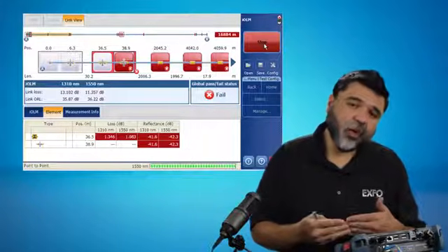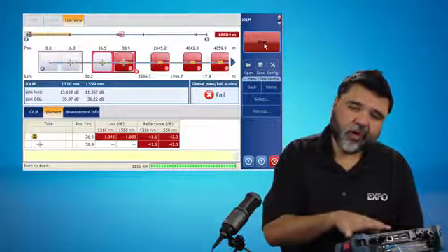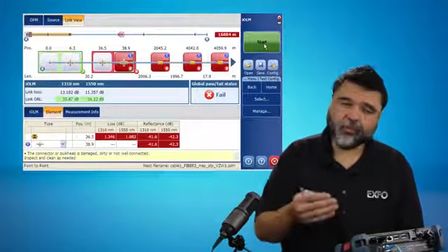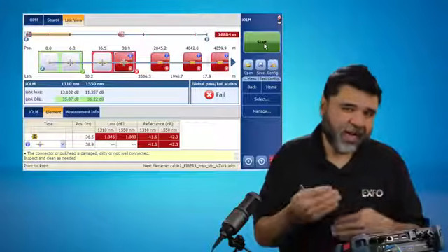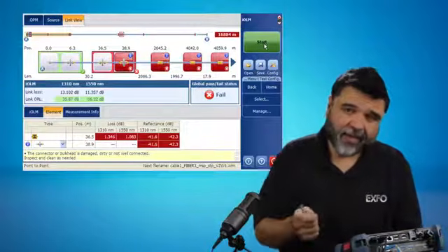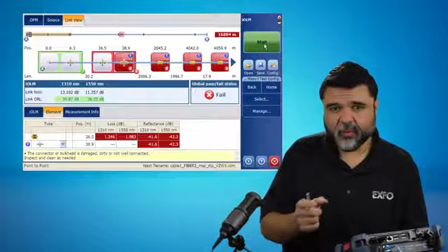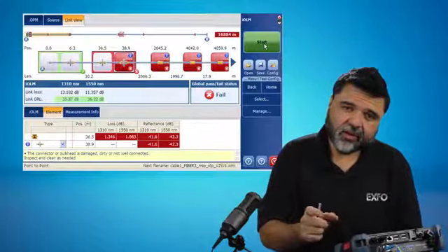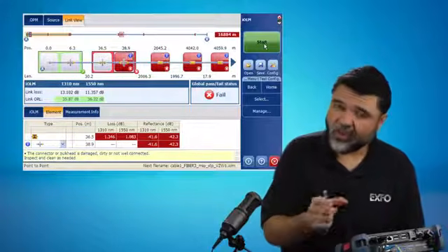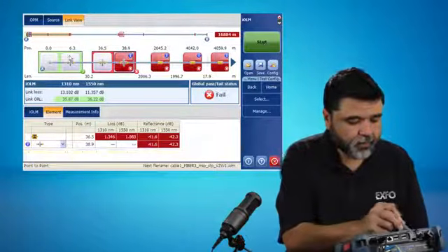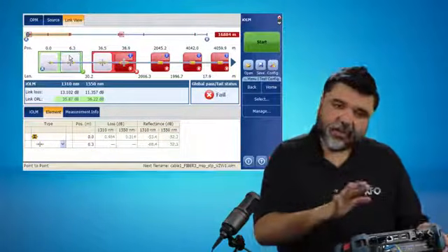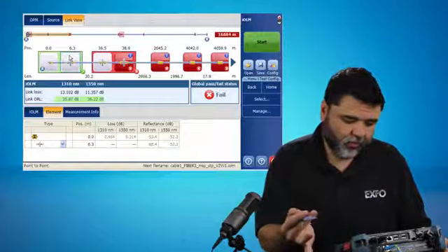And so what this is doing is, if you were to try to do this with an OTDR, you would have to take many tests over both wavelengths and then overlay and analyze the data bit by bit. And there's still portions that you're going to miss because you just don't have the ability to look down into the noise like we can with IOLM. And so in this case here, as I click on every different element, it'll give me that information for that.